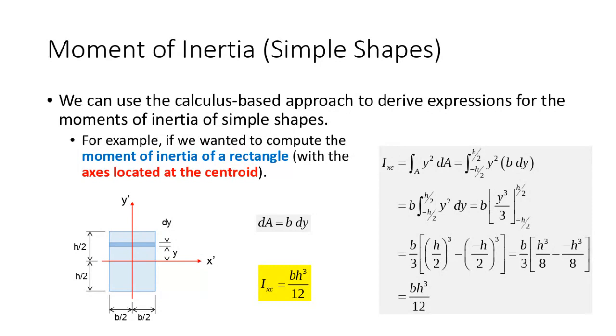So, for example, let's take this rectangle. So how do we do this? So we're ultimately worried about, let's say we're trying to find the moment of inertia with respect to the x-axis. Ultimately, what we're trying to do is complete this integral, the integral of y squared dA. And so we need terms for these expressions.